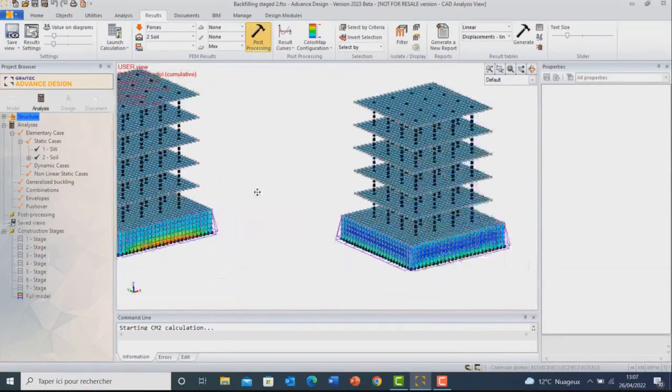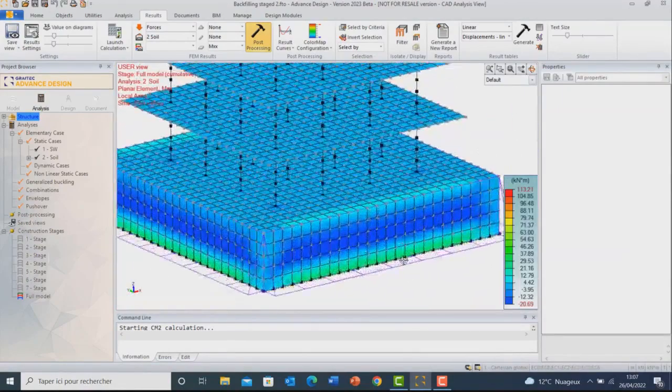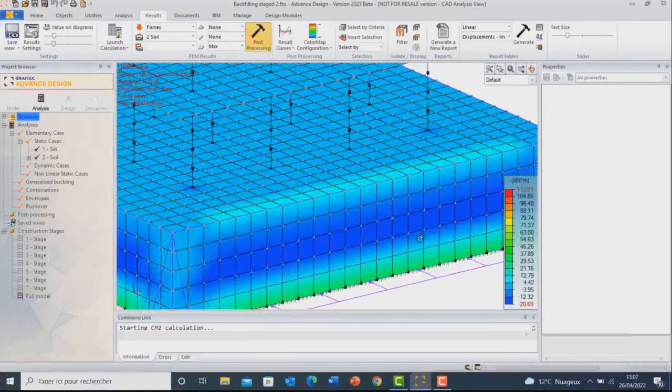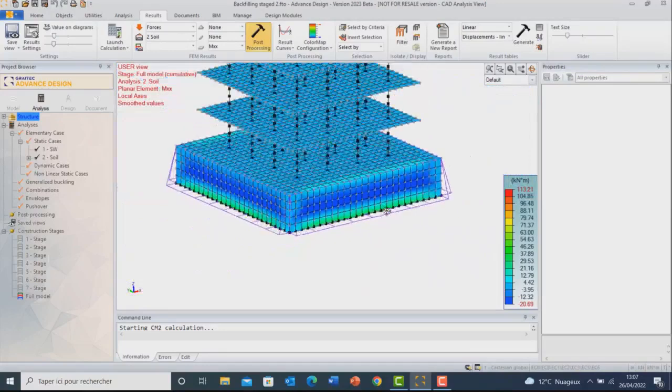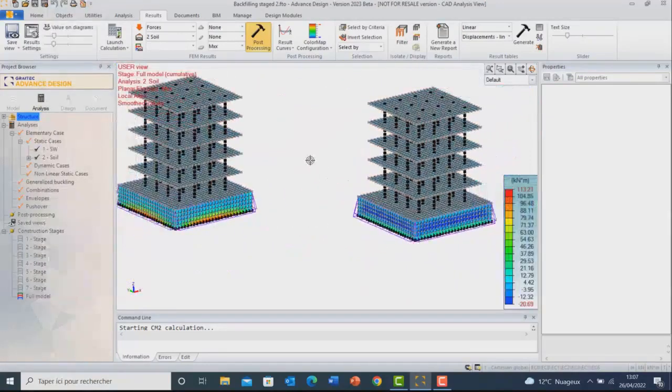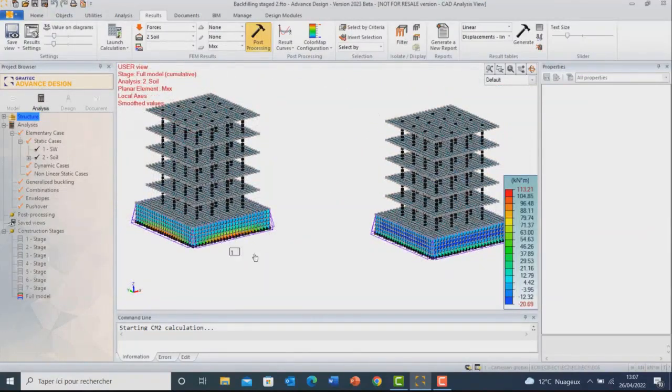Whereas if we want to see the results in a classical analysis, it's clear that this basement wall is supported at 2 points, on top due to the presence of the top slab and at the bottom level where the foundations are. So here we can clearly see the advantages of using stage construction for such a case, to be able to replicate exactly the construction sequence that's occurring on the site.